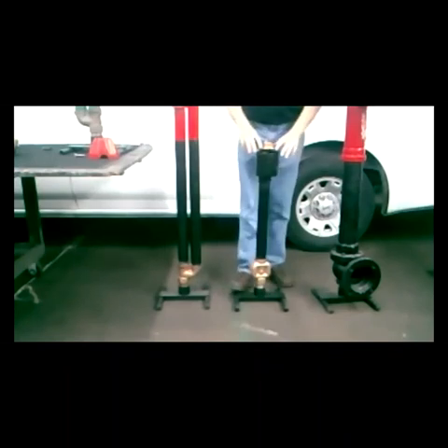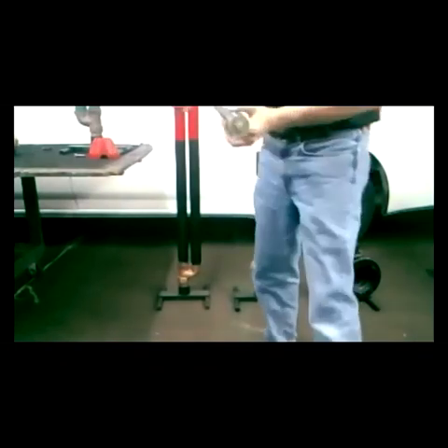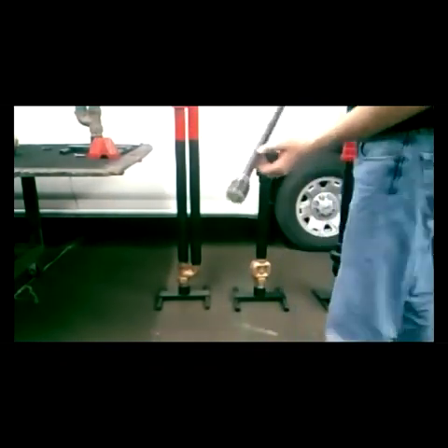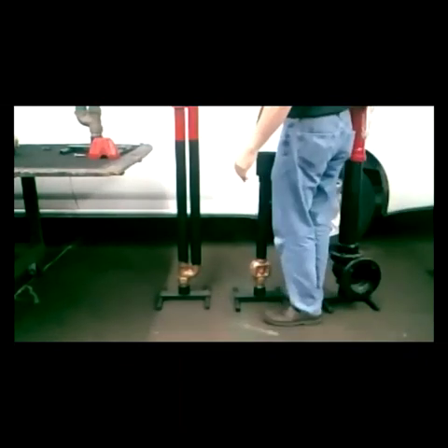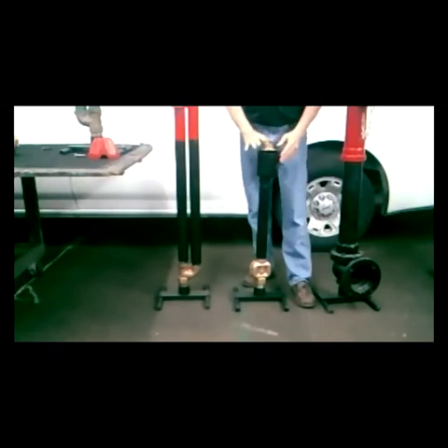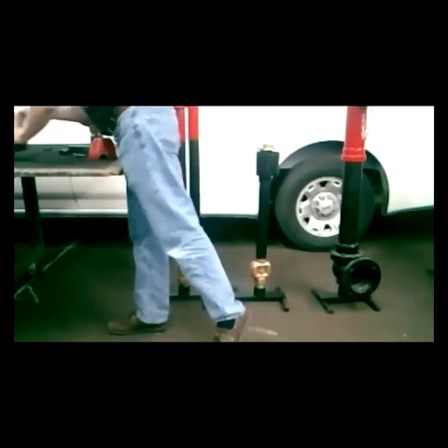To do maintenance, again, turn off the water, 4 bolts, I pull the guts, operating rod, again, the seat here, I have 3 O-rings and a seat. I get a repair kit, I do the repair, I put it back together, and away we go. So this is for the cold climate. For the warm climate, it's the TF550.